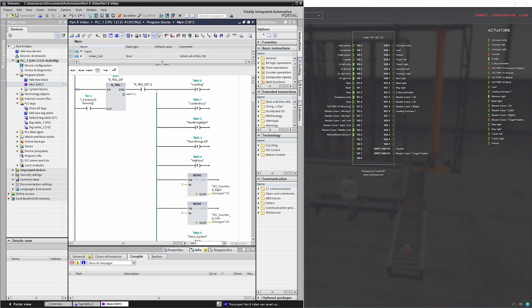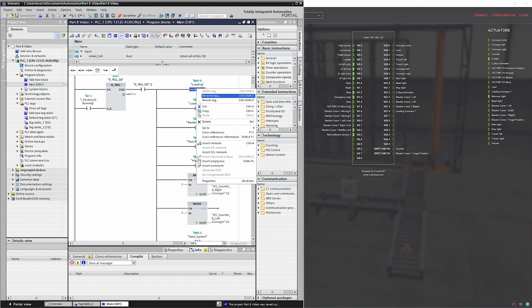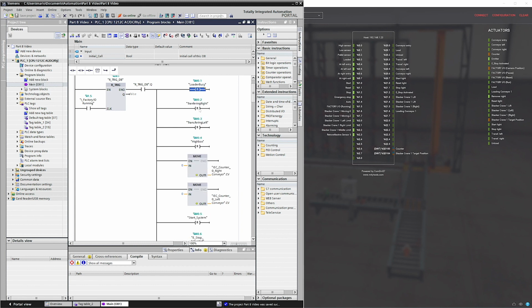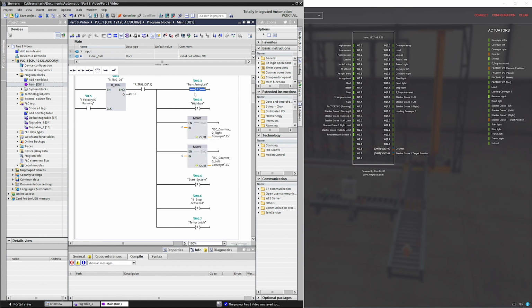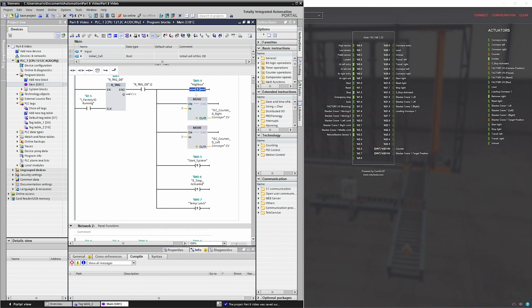There's actually not much ladder logic code to amend, but the first thing we should do is tidy up the code in the first network, as the resets are getting a little complicated and taking up a lot of room on the screen. So let's make a start. We need to delete all 8 resets and replace them with a single function reset. So let's right-click on all the reset coils and delete them. Here we go.